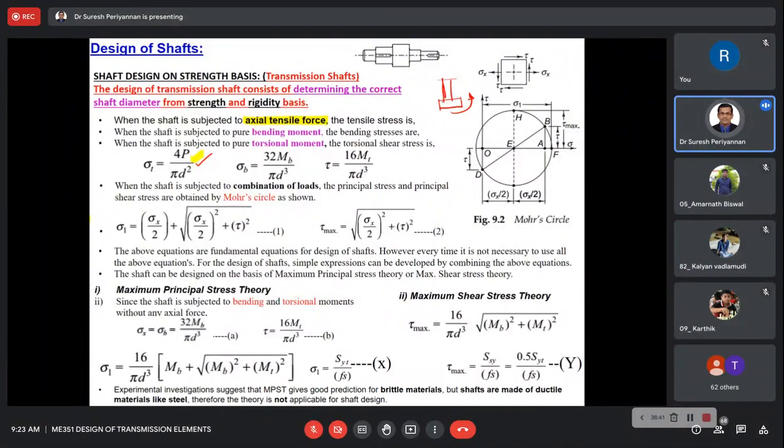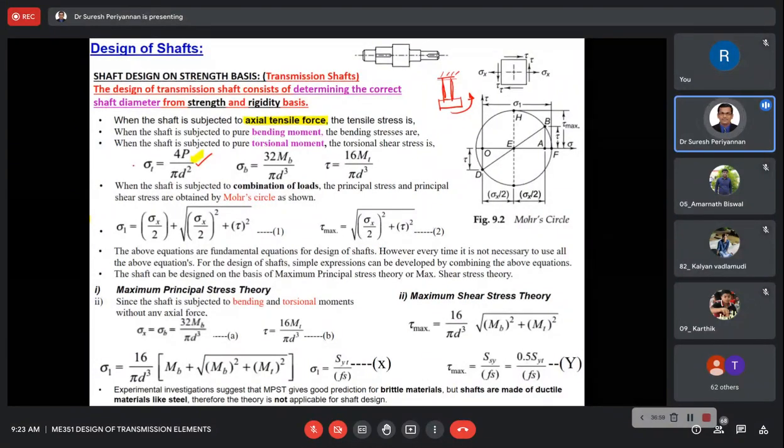When the mechanism rotates, with the shaft in vertical condition, the shaft is subjected to direct tensile load, and it is also transmitting power. Then in this case we have to consider torsion as well as tensile load. But this formula is especially for static load condition. I mean, the first formula we can use only for static load condition.